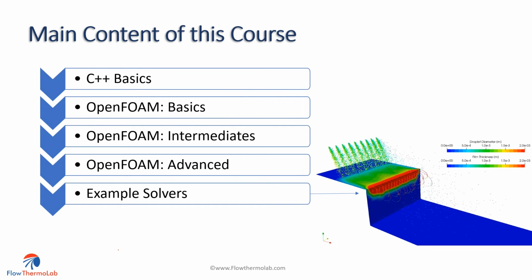Or on the much more complex side, we could do something quite advanced where we come up with a new solver. This is capable of coupling DPM, so discrete phase modeling, Lagrangian particle tracking approach, with a Eulerian thin film model, so ETFM. And within this solver, we're going to introduce capability for tracking Lagrangian spray injections to capture things like secondary breakup of droplets injected under a high velocity crossflow.